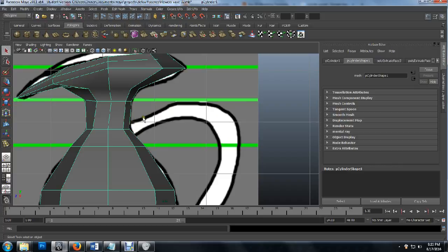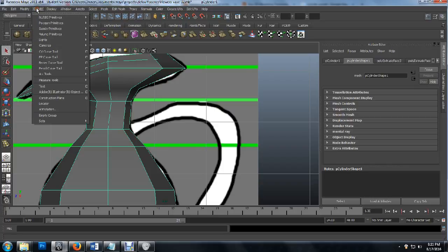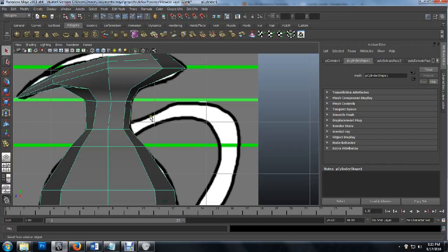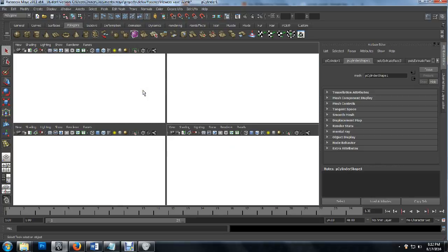individual faces and just create our own polygons to map this and then create its own structure and do some extruding. Either one of those are fine. I'm going to do the cylindrical method. So I'm going to create a cylinder and drop it in here, and then I'm going to start messing with the vertices. But before I do that, I want to go over edge flow real quick.